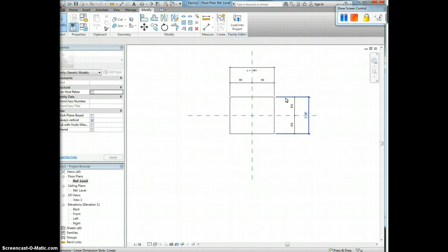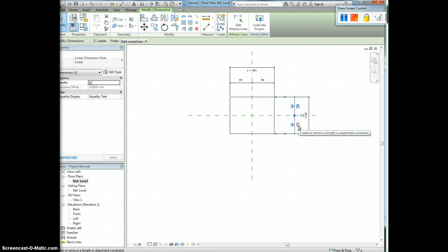Okay, I'm sorry, we need to uncheck this lock, because once they are locked, you are not allowed to change it. Because I clicked on both sides to lock, that means you cannot change any of them. Then the overall length also cannot change. So uncheck the lock sign on the equal part. Uncheck this, then you can turn it into a parameter. If they are locked, we cannot make it a parameter, because a parameter is something that is supposed to be changed later on by the user.